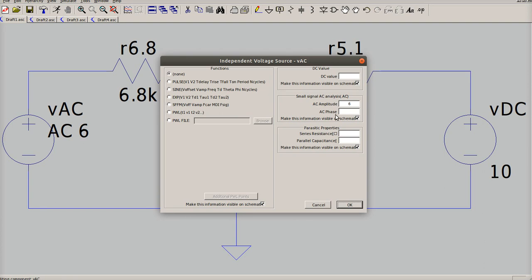One of the things about LTspice that we can do is they call it amplitude, and amplitude is really volts peak. But instead of converting this to a volts peak level, because I know it's RMS, I'm just going to use the 6 as my RMS, and I'm going to pretend this is RMS. Because if you put in peak, you get out peak voltages and peak currents. If you put in the RMS value, you get out the RMS voltages and the RMS currents, and that's usually